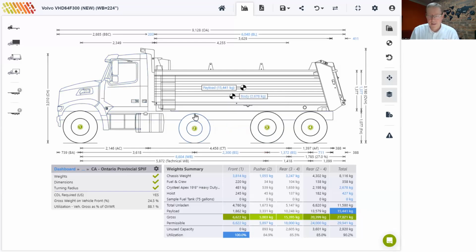So that is maybe answering one part of that question, but there are also areas where we measure the interaxle spacing, and if the distance is less than a certain distance, it will reduce the carrying capacity of, say, the driven axles. So that is taken into account, and it would be interesting to hear from the person who asked that question if there's a particular example where maybe you couldn't see this. Maybe we can take that offline, and we'd be more than happy to work through your calculation with you.